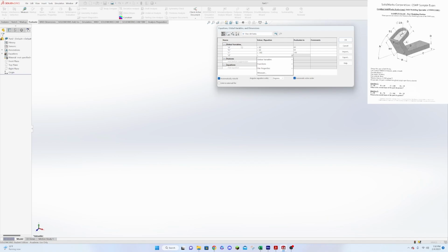D is equal to 19. I'm going to add in another one because I've built this object before, and there's some parts where it's actually handy to have a value that is half of what B is. So you can see for determining the radius up at the top and the length of that piece up at the top, having that value is useful.